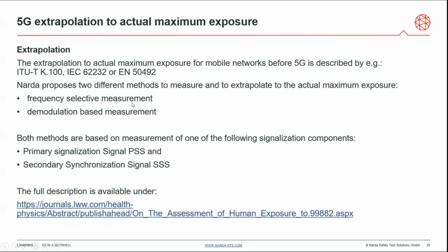signals, if the traffic load is not too high, and you can see in frequency domain and in time domain. So it's a combined method with a scope mode, time domain, oscilloscopic presentation of signals, and frequency selective measurement, so that you see the complete signal in time and frequency domain, the up and down links, because we're talking about TDD, so you need to exclude the uplinks, the user equipment, which could be dominant if there are any smartphones, mobile phones, or modems nearby your measurement position.